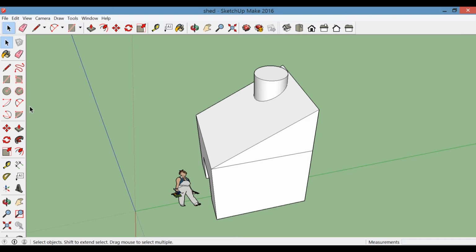To finish off, there's a few remaining sketch tools we have to go through, and let's start with the curve or arc feature. So the curve or arc feature allows you to sketch just a section of a circle. So first you would define the start point, and then the end point, and then you move your mouse to indicate the direction and height of the bulge, so how far your arc will stand out. This bulge and its height can be specified using the dimensioning techniques we talked about earlier.